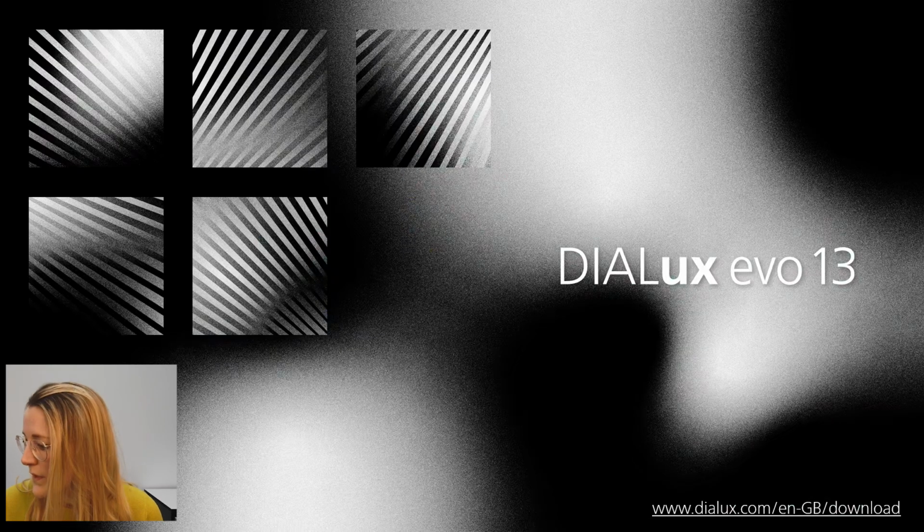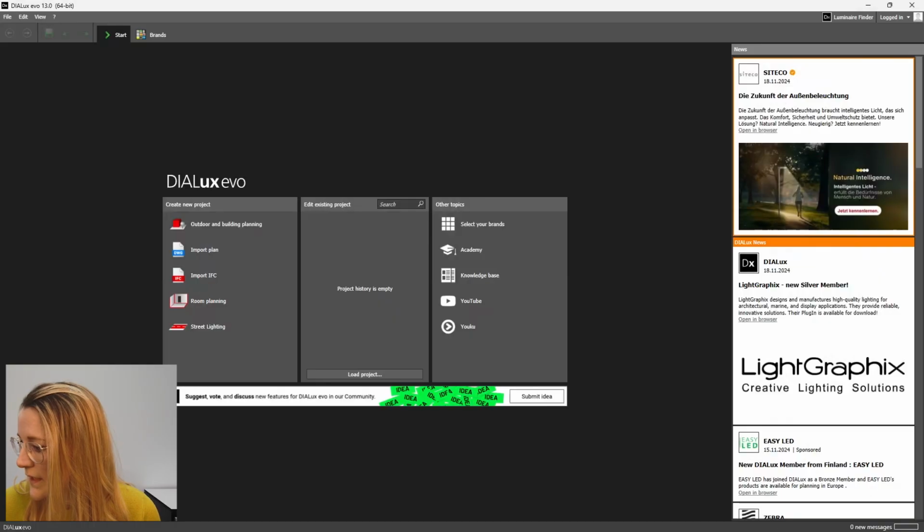Okay, so I will show you now the import function in DIALux. I have started it. One hint, as you have seen, it is now DIALux EVO version 13. And I have the Pro version here, so I can use the import button for IFC files. That is what I want to show now. I can do drag and drop, so it's like the import button.